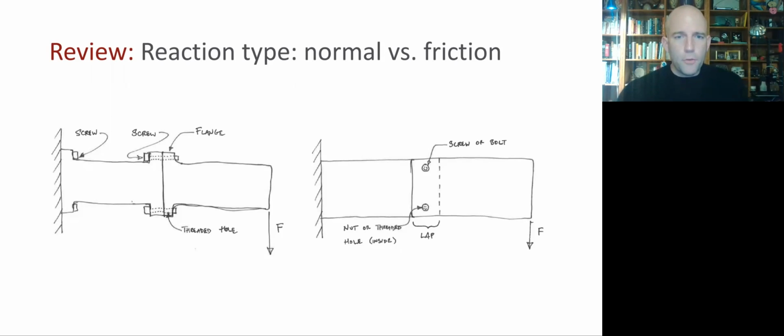If we loosely tighten our screws or bolts, or just put some pins in there, we'll be loading those screws and bolts theoretically in shear, more likely in real life in some complex bending. And our fasteners aren't designed for that. They generally don't like that, and that's going to be a weak point. We need much bigger hardware for the same reaction moment at this connection.